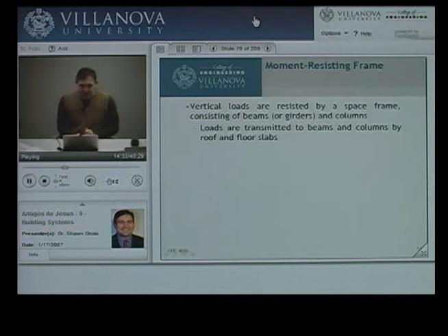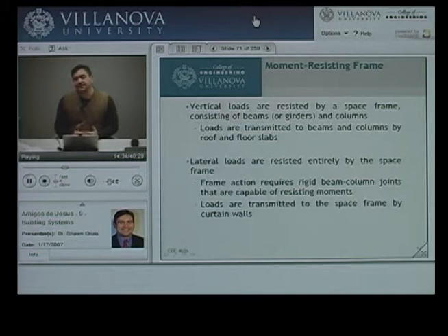That's kind of self-evident. If I think about lateral loads, what I in essence have is a frame system with moment connections, or rigid connections, to resist lateral loads. If you think back to structural analysis, the easiest way to look at this is to take a frame, and instead of just putting vertical loads on it, let's also put lateral loads on it. What happens is the beams and columns deform as an overall unit. The structure deflects to the left or to the right, depending on which way the force is acting.